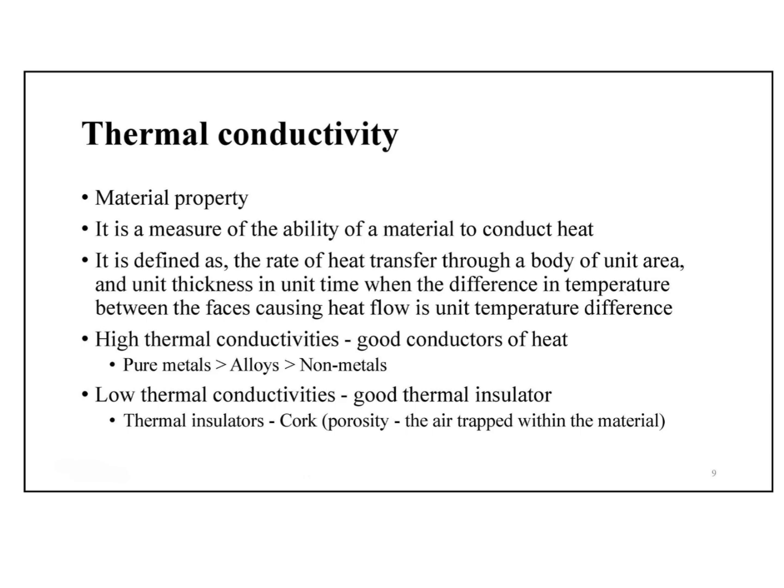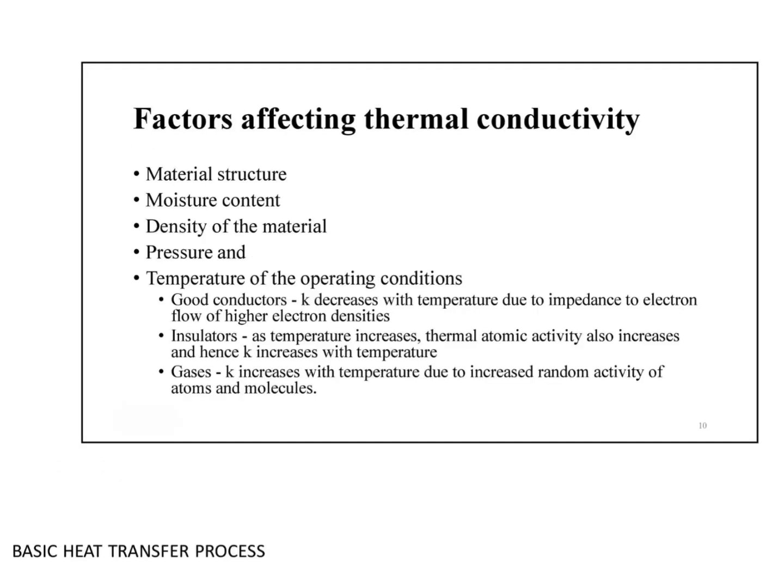Moving to next slide. Factors affecting thermal conductivity. Factors include material structure, moisture content, density, pressure, and temperature. For conductors, conductivity usually decreases with temperature. For insulators, it increases. In gases, it also increases with temperature due to higher atomic activity.